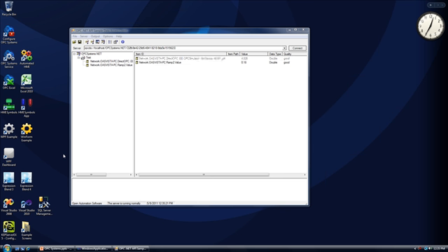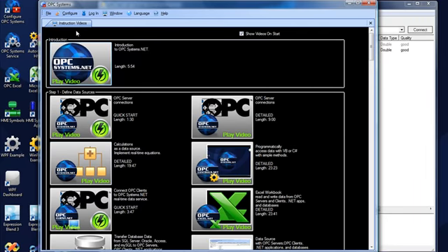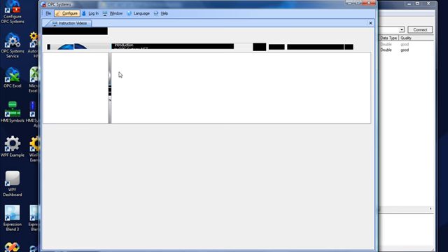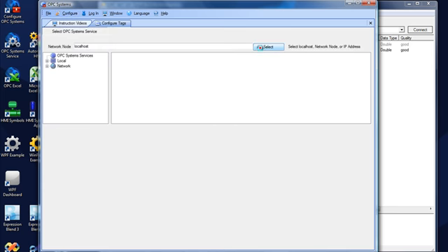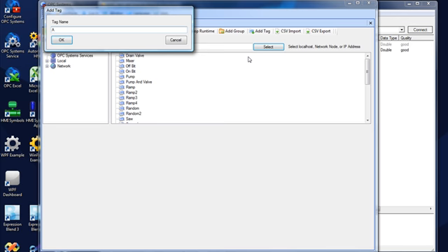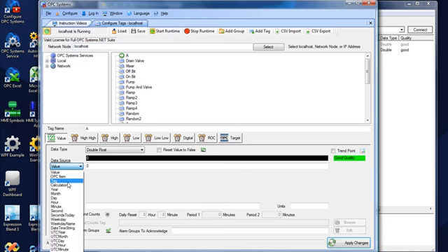This allows us to specify to connect one OPC server item and automatically transfer that value to another item. That is defined under configure tags. I'm going to configure the local service here, and I'll add a new tag. I'll use the tag name A so it appears at the top of the list. I'm going to use the data source of tag.